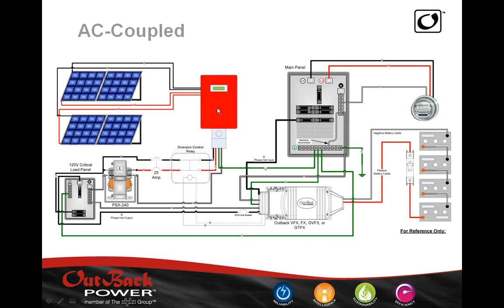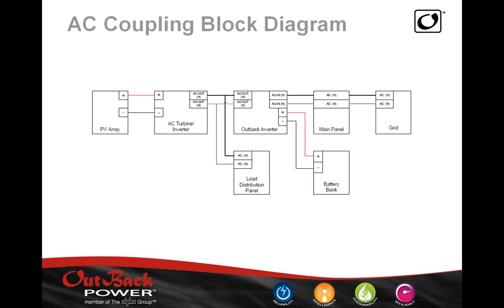The battery-less inverter will then notice that it has a 120 volt, 60 hertz signal, and after a 5-minute wait period, it will begin. If this is during the day, it'll allow whatever energy is being harvested from the PV array to flow onto the loads. And if the failure happens at night, then the batteries will be supplying the power to the system. Here is a block diagram that shows how the energy flows.